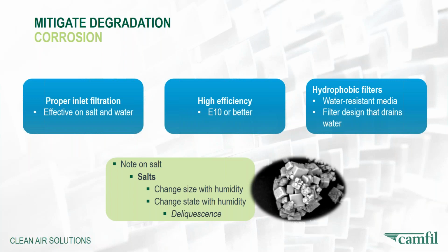And most importantly, we need hydrophobic filters, which has 2 components to it. One is a water-resistant media, so that any water, any salt water that may be present in your application doesn't migrate through the air filter media. And also, if we stop that water, we need a robust filter design that will drain that water away so it doesn't create a short life or pressure drop problem.